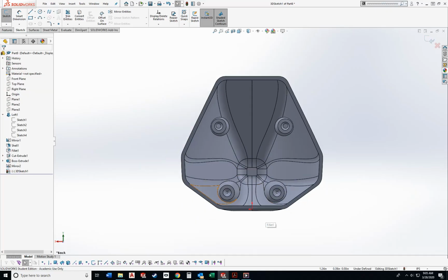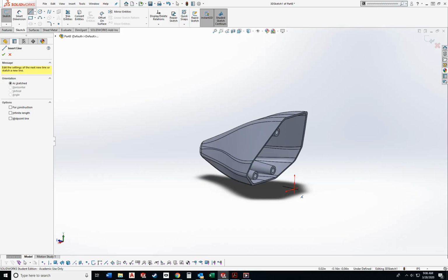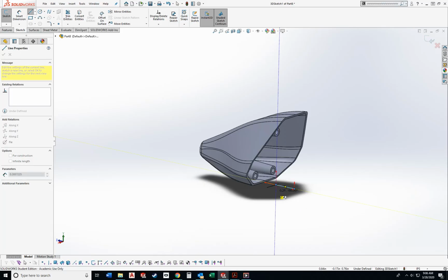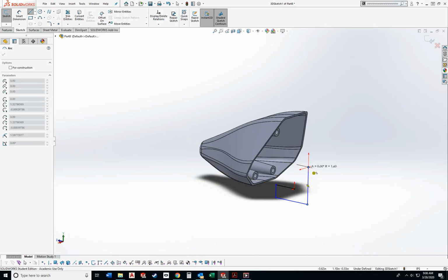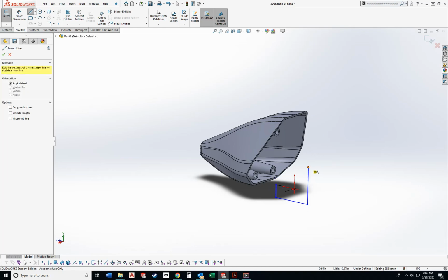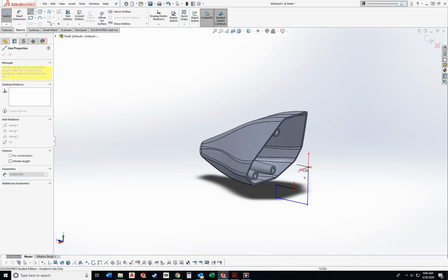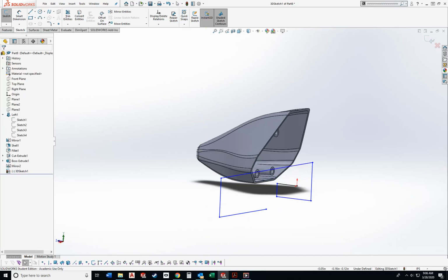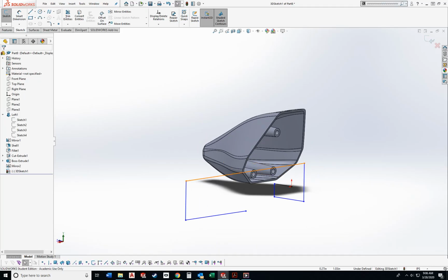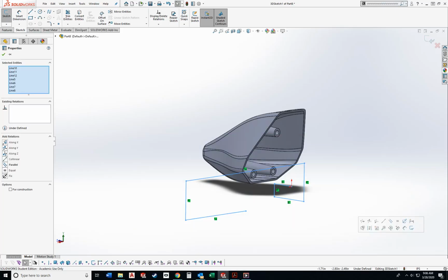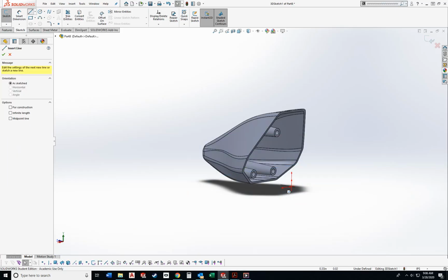Now, giving myself an ISO again, if I go back into my line tool and I click Tab, now I'm in the YZ plane. So that's anywhere in this plane here. So if I go back to the XY, let me click this, Tab to the XY, and now it's like I'm drawing back on the right plane. So the YZ in this drawing right now is going to be more like our right plane, and the XY is going to be more like our front plane. So let's use that knowledge to go ahead and create this landing gear.